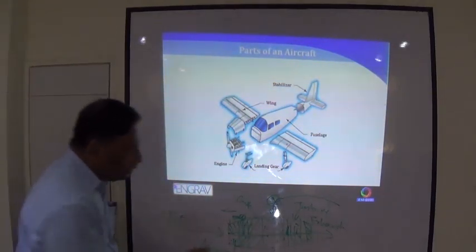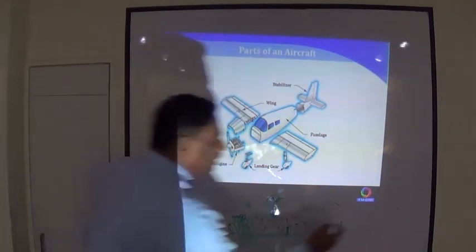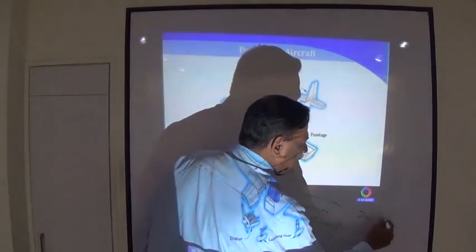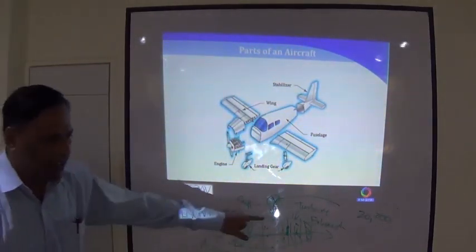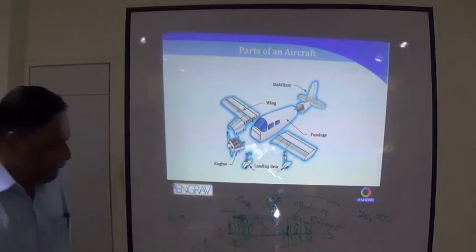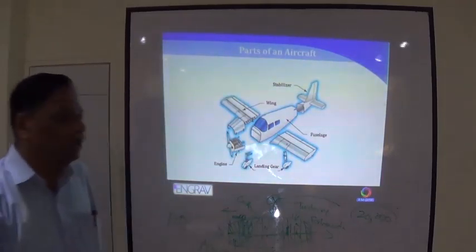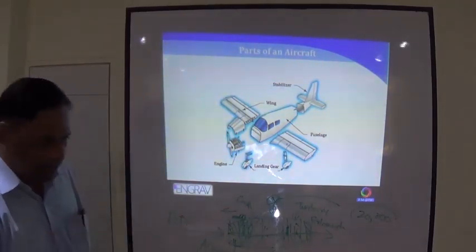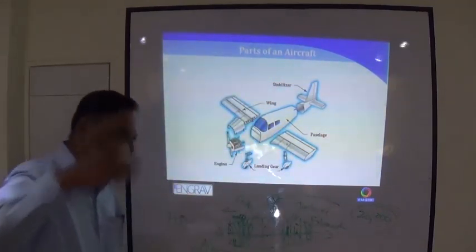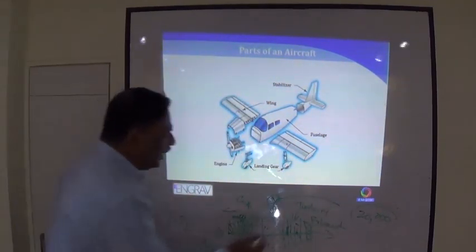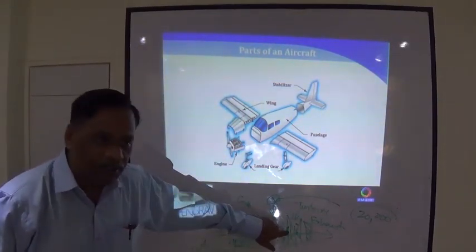So this is one of the turbine blades, and each turbine blade has a life, maybe 20,000 cycles. So this blade has to be replaced after every 20,000 cycles, basically after every 20,000 starts. If the software is not good or the user did not change it after 20,000 cycles, the blade will continue to fly for 30,000, 40,000, and one fine day it will explode in the air. It will just detach from the shaft.